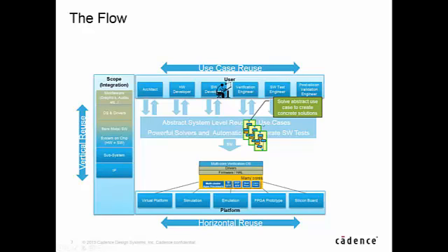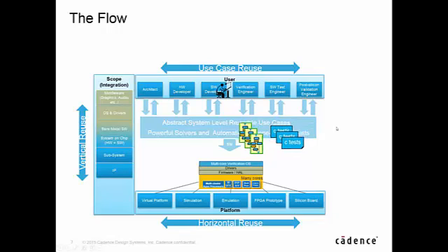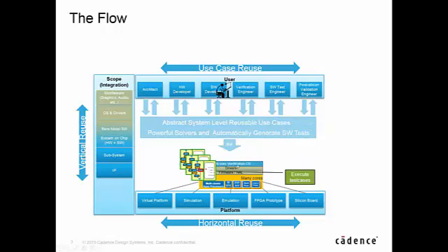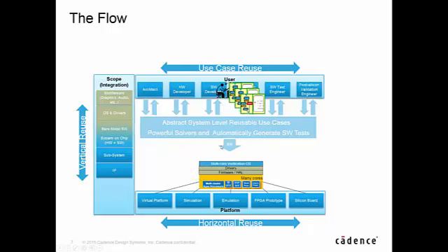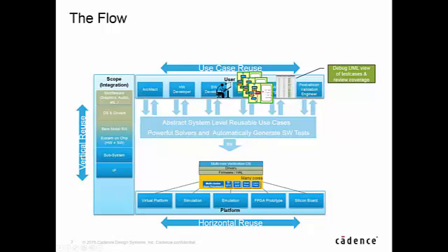So those concrete solutions can be in turn generated into C-tests. The C-tests can be executed on the different platforms, and then the results of those C-tests can be used in that same abstract form for debug and analysis. So you can look at your coverage, you can look at the actual execution that occurred of the test and go in and debug it at the abstract diagram level or down into the detailed C software debug kind of level.